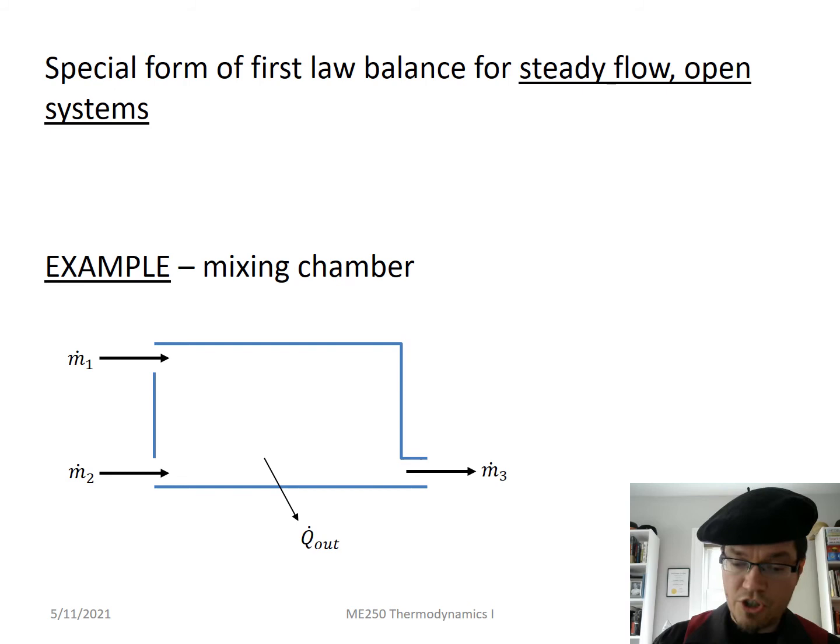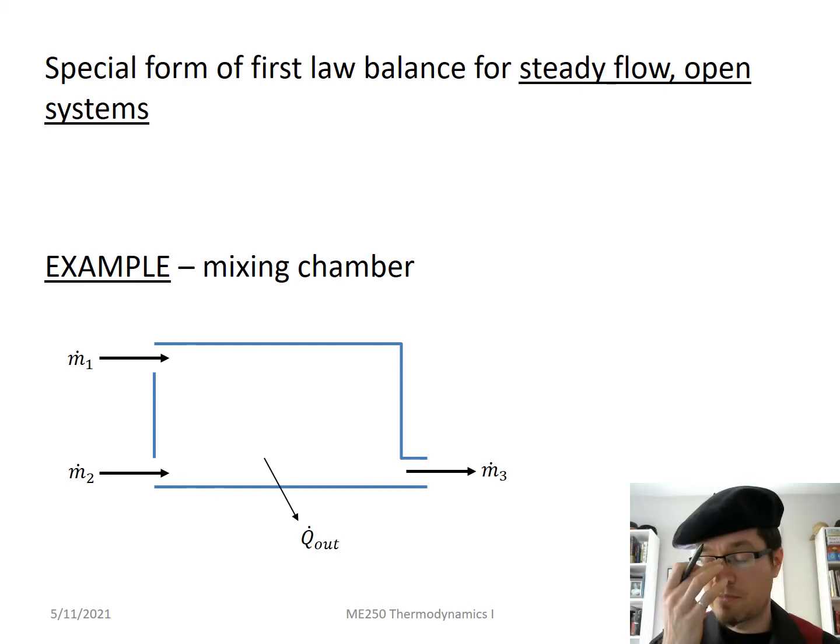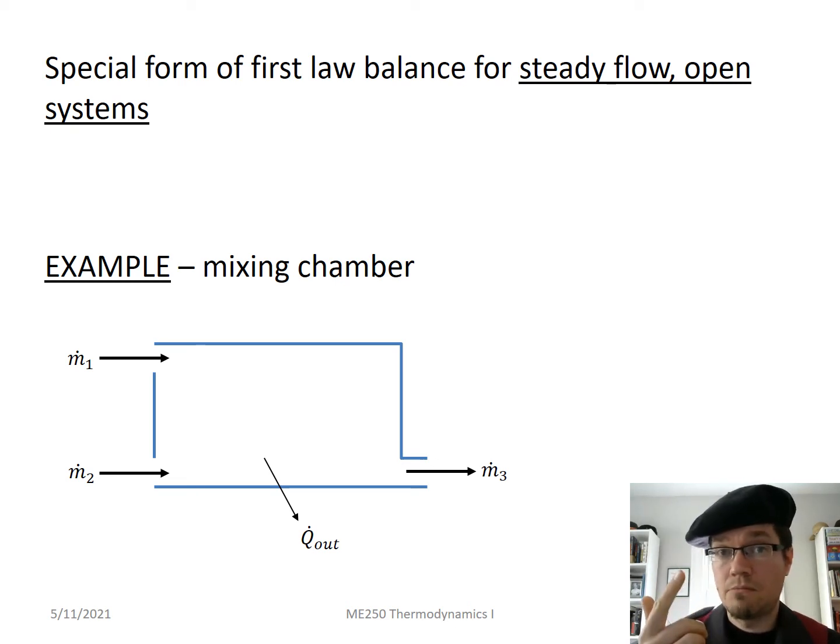So just like we wrote the energy balance for a closed system, let's now write it in general for an open system. Let's specifically think of an open system with steady flow. In minus out plus generation equals storage. And since we're talking about energy, we can't have generation. You can't create or destroy energy. So in minus out equals storage or change.